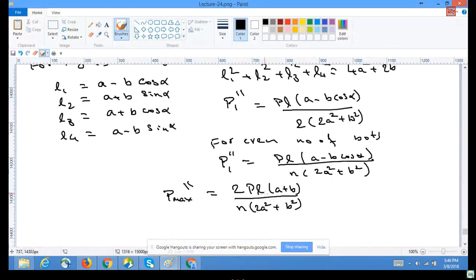And once you know this, then you can apply your principal shear theory, and the corresponding allowable stresses can be applied. So this would be very useful if you are doing an eccentric loading with a circular base, such that the angle is alpha from the vertical for the first one, as shown in figure B.